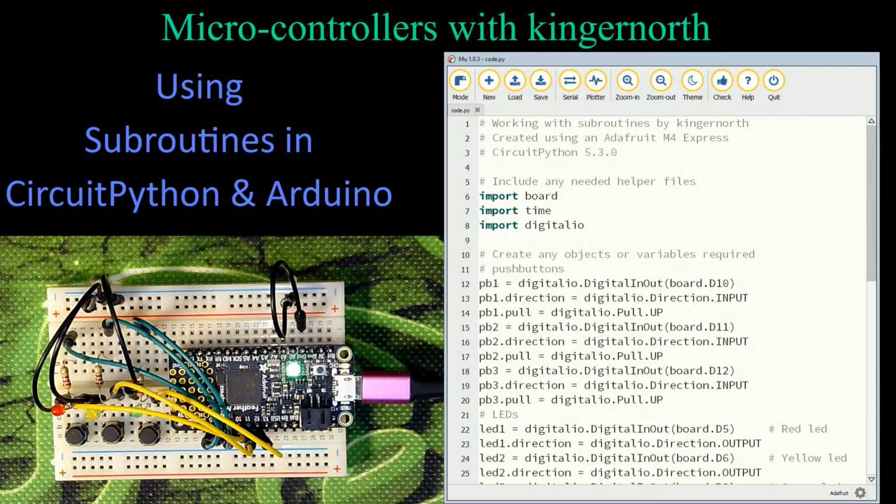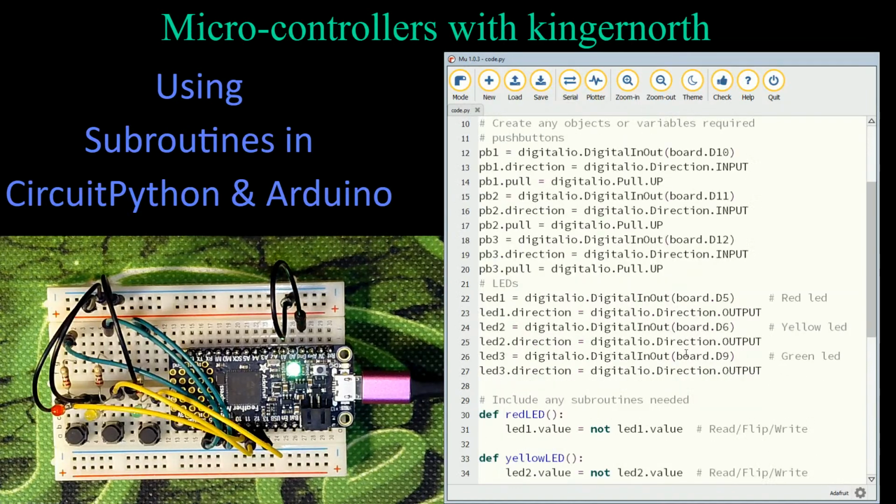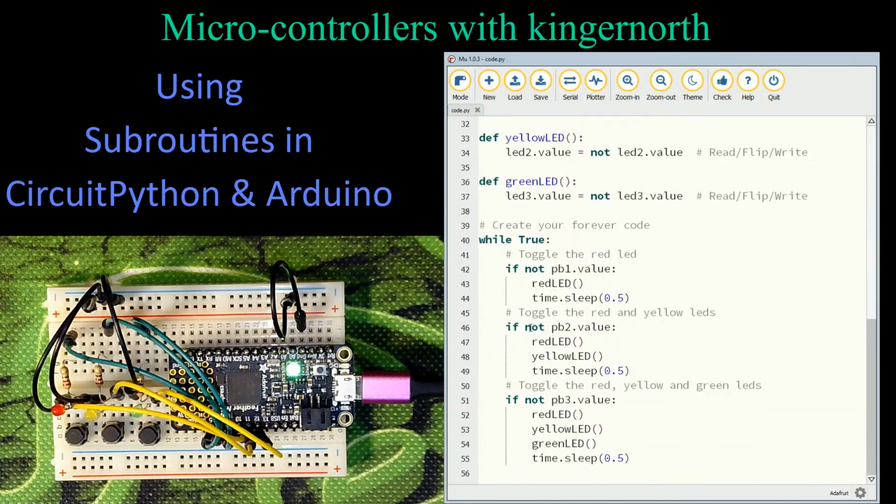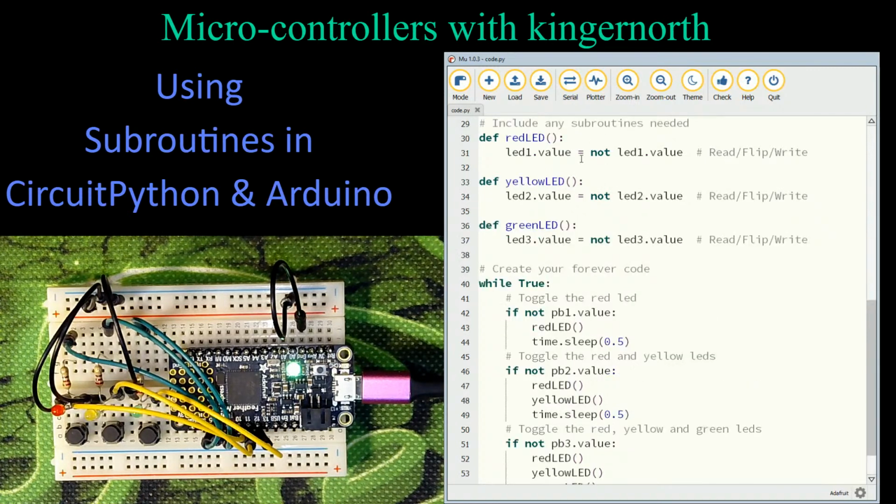So I don't know if you guys have any more questions. I saw Bruce's one question there about the timers. If you look at my code, I'll just show you that in the program code here. The timing values are in the push button segments and not in the subroutines. So the subroutines execute very quickly with just a single pause based on each button. Okay. And that's basically what subroutines are. That's what subroutines are all about.